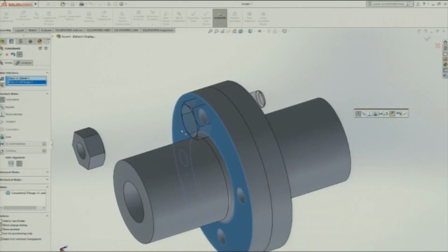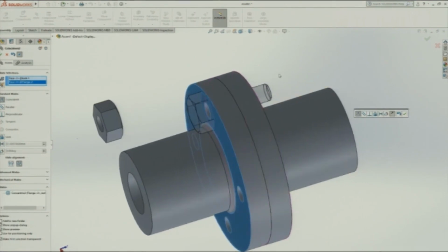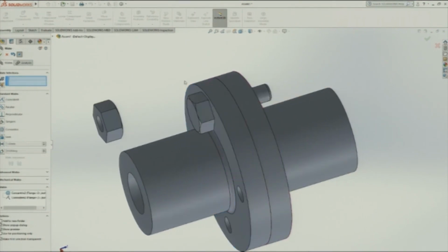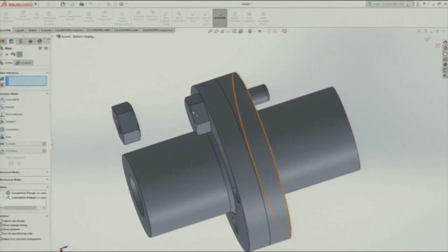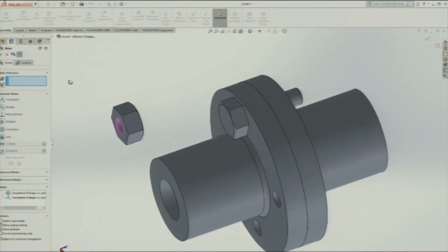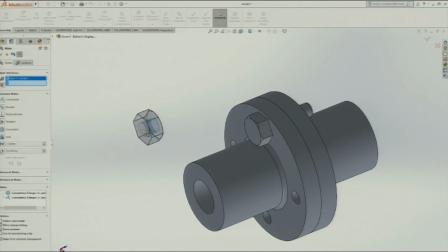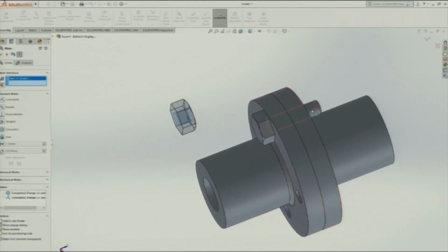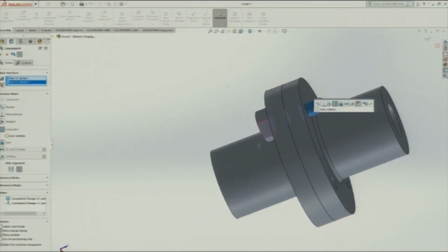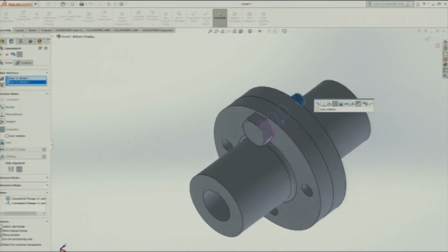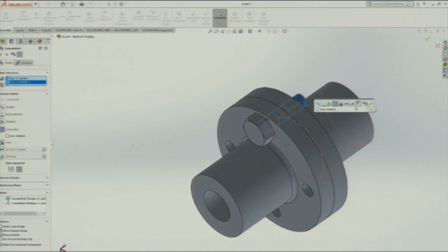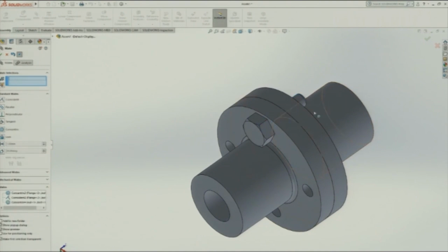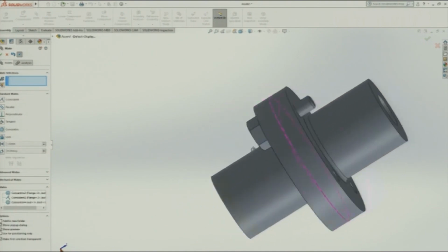This is known as mating. Now, this is done. Now that nut is to be put on the other side. The similar command is used here. I will just put this circle and this circle. Okay. Yes, now this is interesting. Now, where has nut gone? It is mated. This is important to note, since we cannot see the nut here.